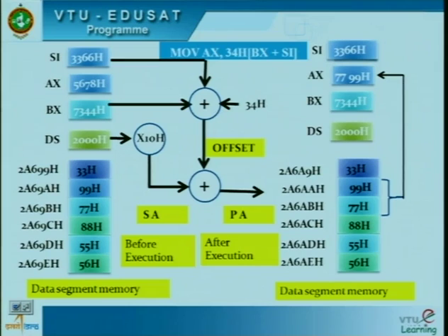Never forget, the bus interface unit acts as an interface between the processor and the outside world. So, whenever the processor wants to access the memory, the address calculation follows the same principle of taking the segment address from the corresponding segment register of the target segment being accessed, and then an offset is added.